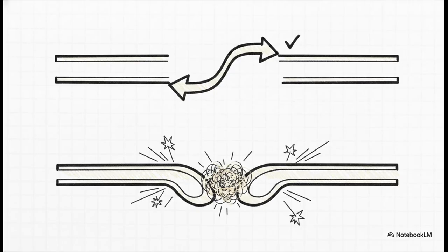So why is the 3D FDTD data slightly lower? It's kind of like a physics mystery. Actually, scratch that, it's not really a mystery, it's just the messy reality of physics. The math predicted a higher coupling strength because it assumed an ideal, perfectly straight path. It completely missed the real-world losses caused by the waveguide actually bending. The 3D simulation, however, caught all those phenomena, the bending losses, the curvature phase mismatch, and the modal dispersion, which gives us a much more highly accurate result.